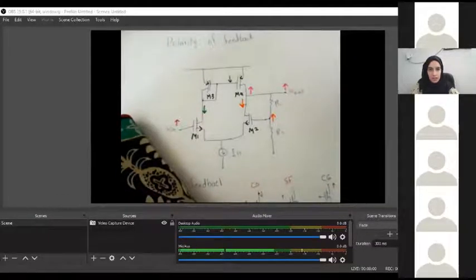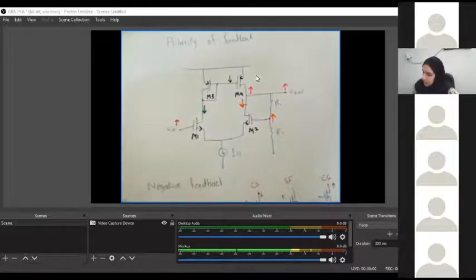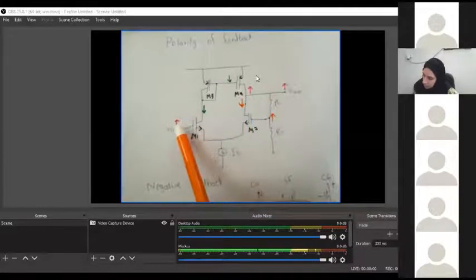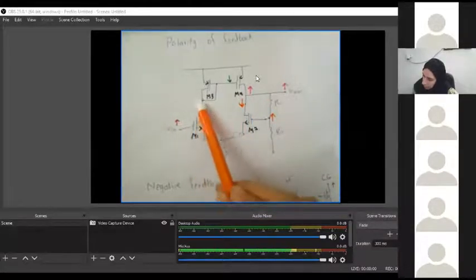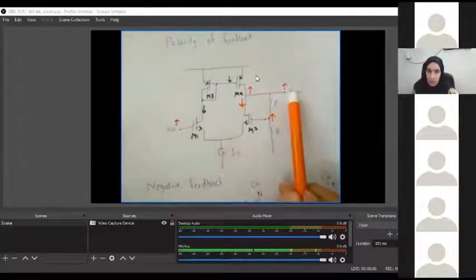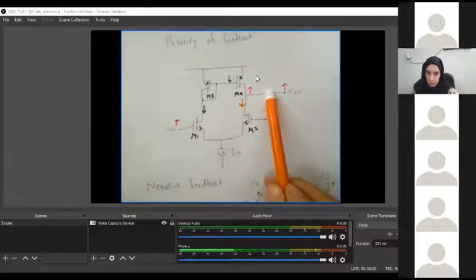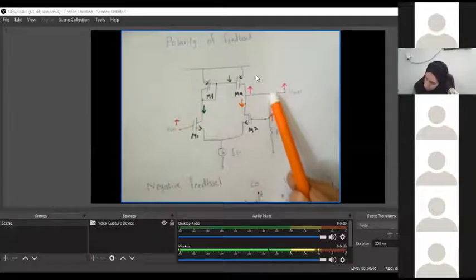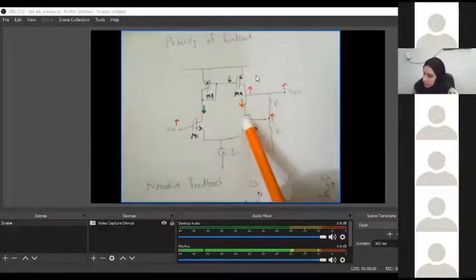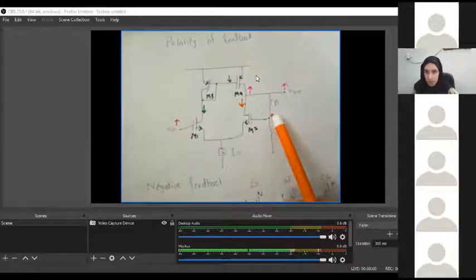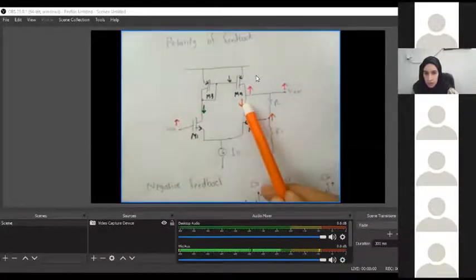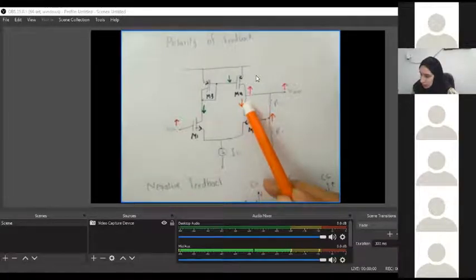Can you repeat the last line? Okay. Basically, again, we discussed that Vn has caused, through this entire path reaching to V out, in the pink line that V out is going up. Okay, now we started from V out and went back through this path that is here. We have seen that this node is also going up because again, it depends on the voltage divider with the V out. Now, VG goes up, it's going to cause the drain side to go down, and the drain side is also connected to V out.